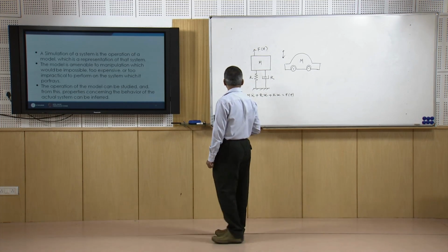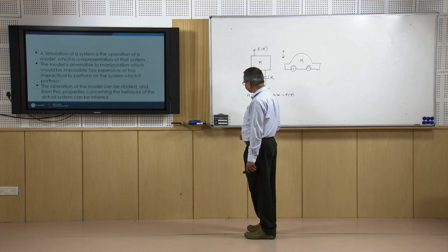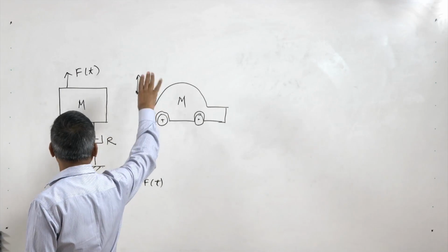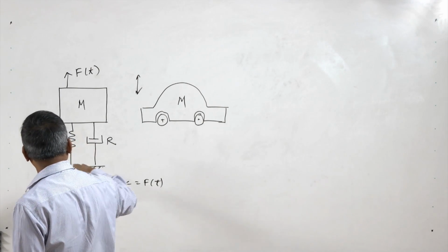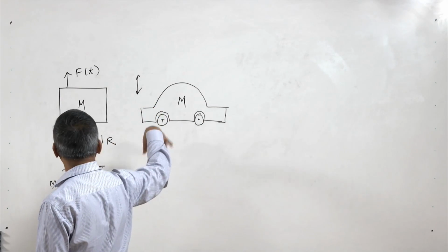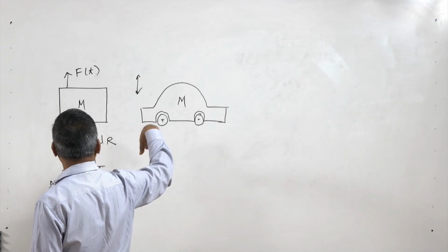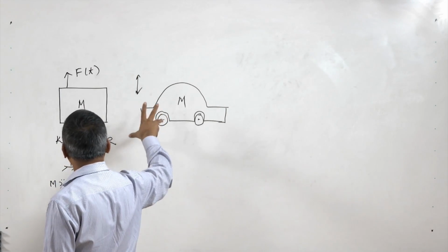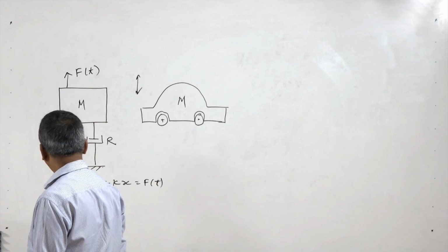So, for example, say I want to see the performance of the different stiffnesses on the vertical motion of the car here, then naturally if I am doing it on the real physical system, I need to replace the suspension system, and then I want to see the vertical motion here, and again apart from those hardware, I also require some measurement devices for measuring the vertical motion.